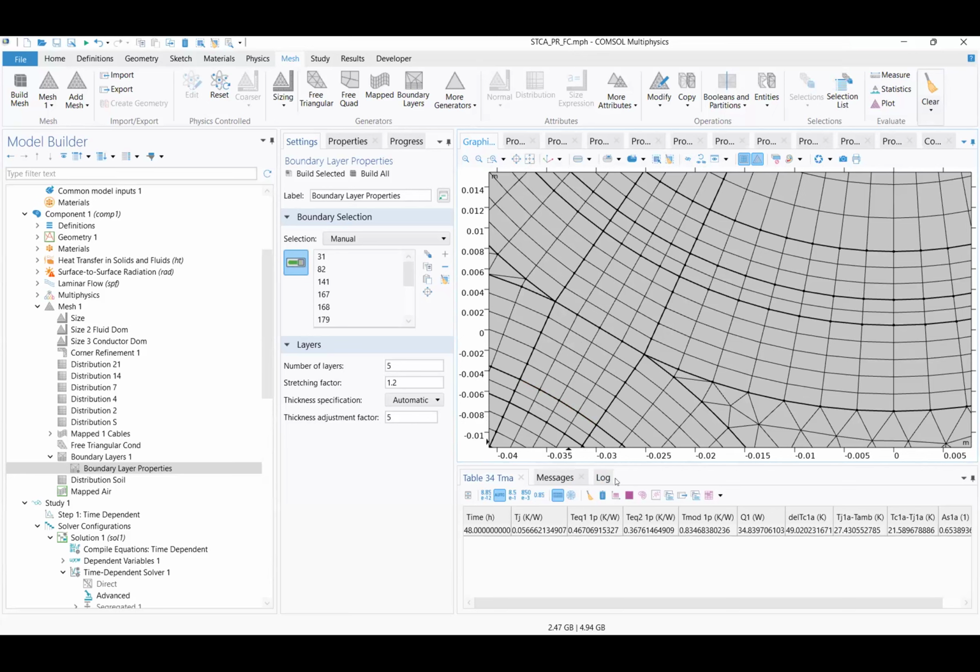You see, as we approach two circles touching each other, at some point the triangle, right here, is becoming degenerate. The next one will be impossible. It will have a very small area. And if you remember, in all the finite element matrices there is a division by 4 times the area.